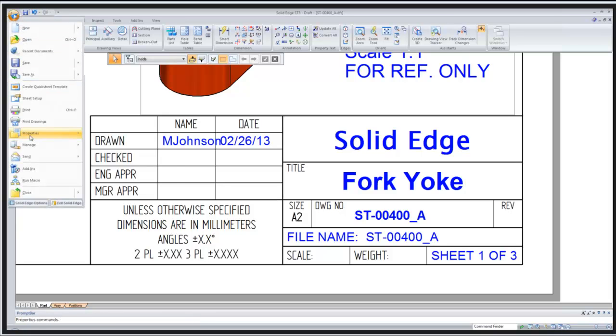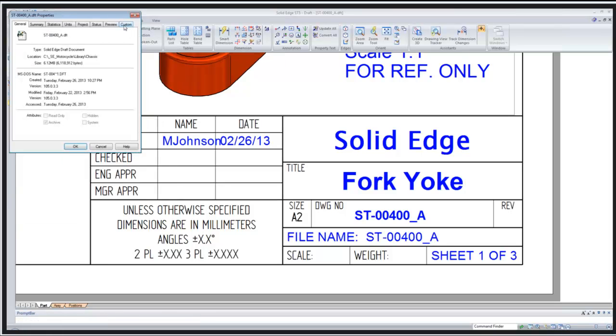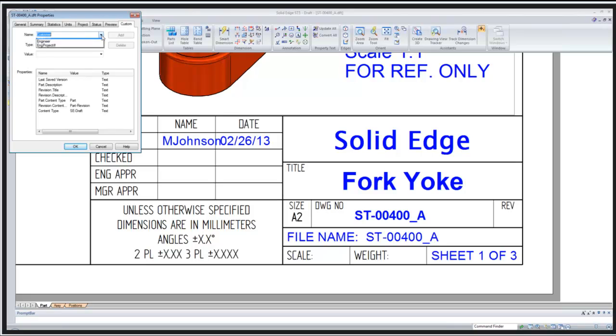And now when we go to File Properties, under the Custom tab, I made 3 new properties here. I've got a customer name that we always use, and here's a list of customers that can be defined. I'm going to add that property. There's an engineer tab, and you'll note that this one by default put Joe in for a value, but I can pick the different engineers, or I can accept Joe as the default. And also engineering project number, and it's got a list of project numbers.